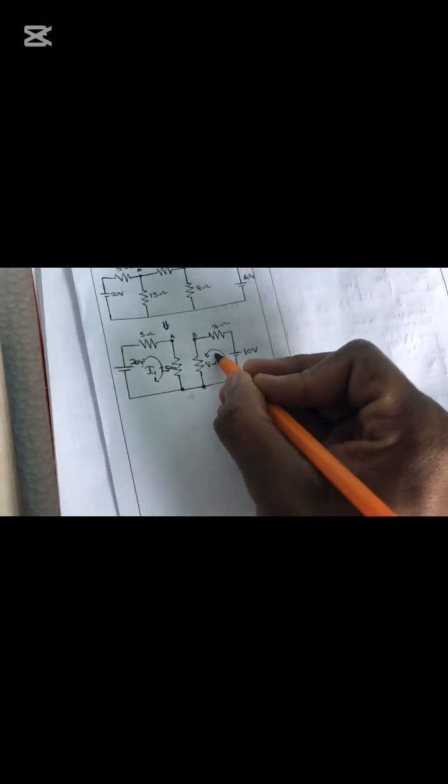The currents that we are going to find are the ones that are going to help us find the voltages here, and once we subtract those voltages from the two sides, that will be our Thevenin voltage. The first thing that we'll do using the current divider rule, we'll take this loop here into consideration. We will call this I1 and this I2.